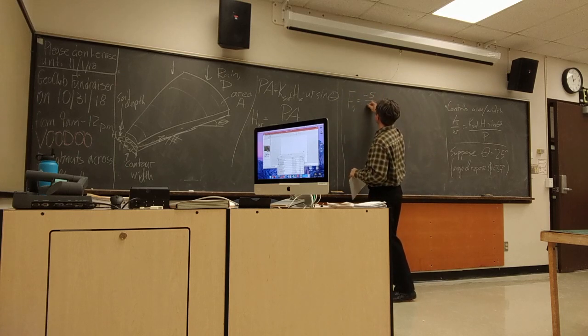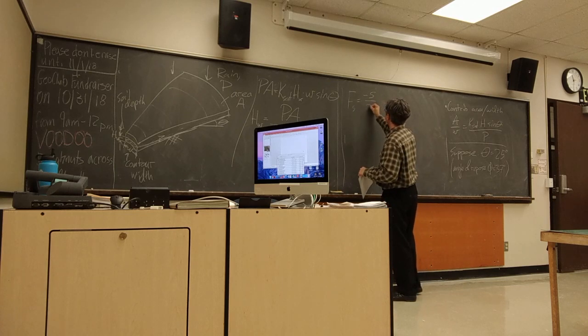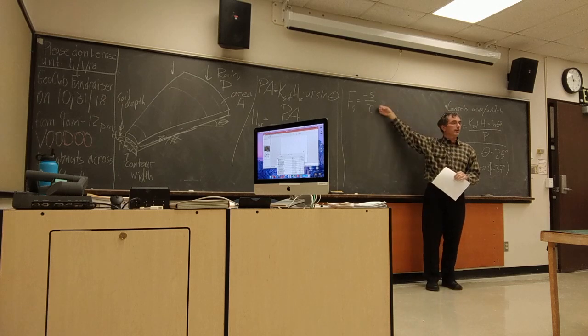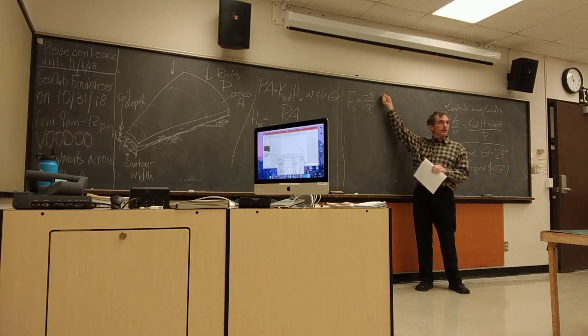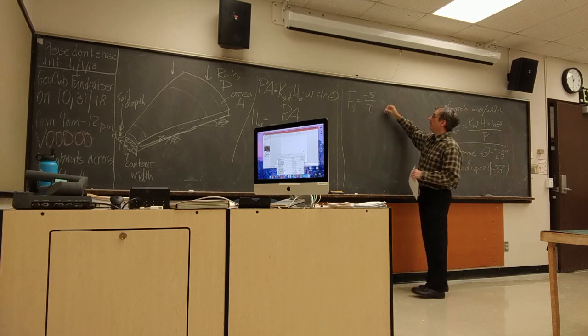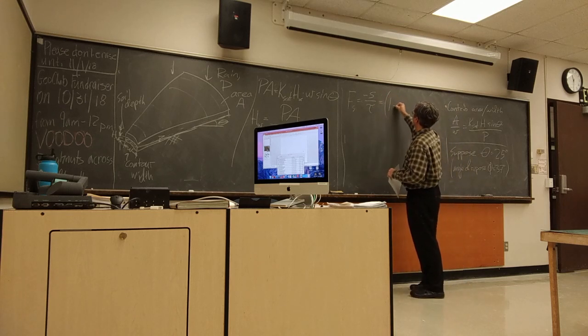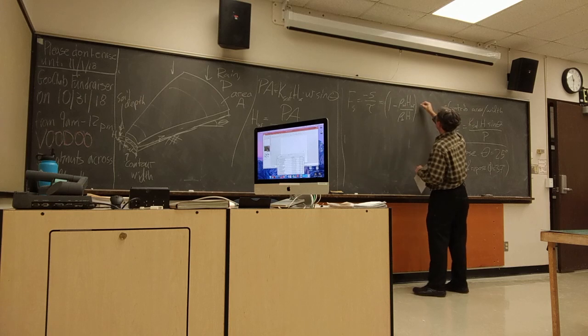Remember, the factor of safety is defined as this ratio between the magnitude of the shear strength and the shear stress. Shear strength was what? That's friction and cohesion. Shear stress is just that part of gravity that's tending to make stuff fall downhill. I had a relatively memorable form.